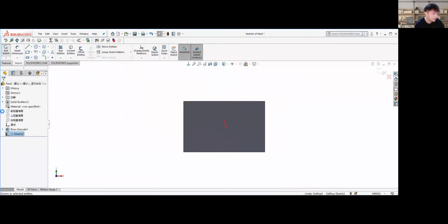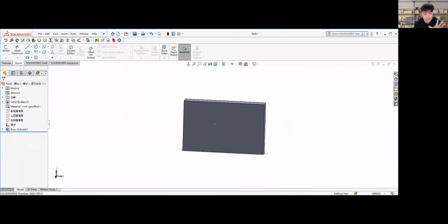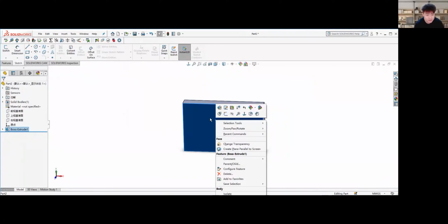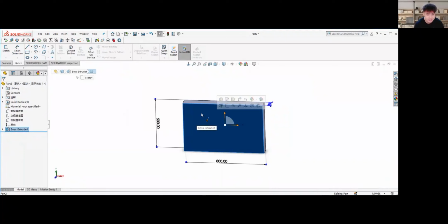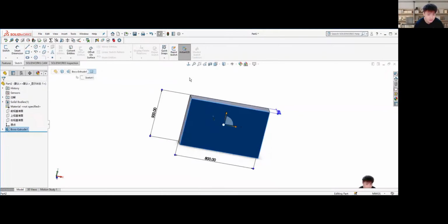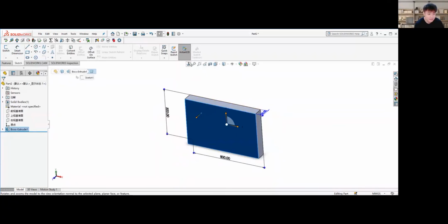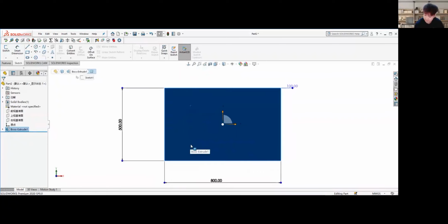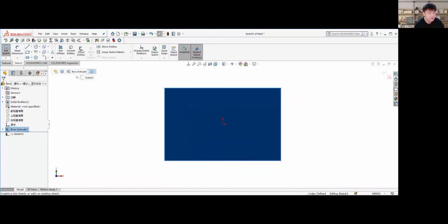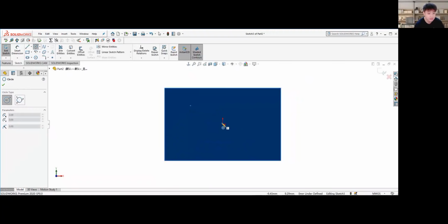From here, from an exit sketch, I want to make a new sketch on it and make a new extrude on it. So what can I do? I select this face, select this view, right? This face right here. Use your left mouse, and then normal to it. Got that? You see that? And then I make a new sketch. Just press the sketch right here. A new sketch, and use the circle on it.